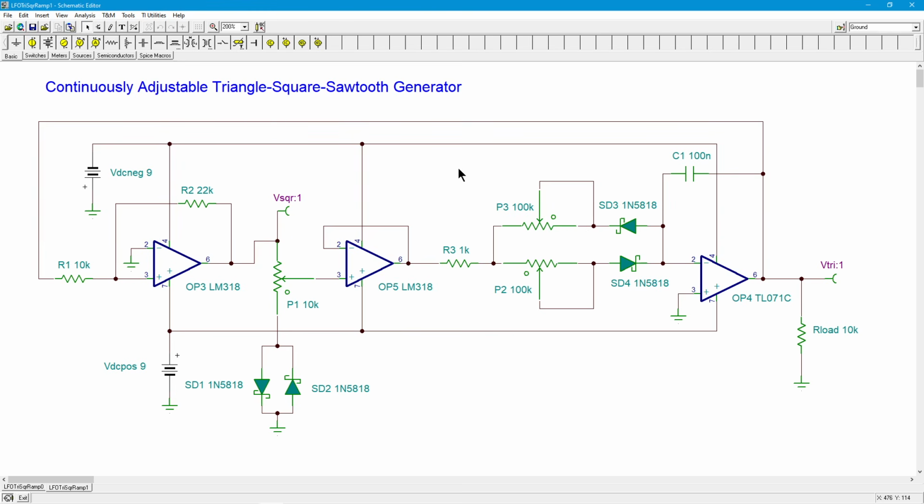Now here's the cool part about this. We take two identical potentiometers. We actually go out and we buy a dual gang pot, right? So two pots on one common shaft. But we're going to wire them as rheostats and we're going to reverse wire them. In other words, if you were looking at the back of this, right, there would be three terminals. You have a left terminal, a center terminal, and the right terminal. So the center terminal is going to be the wiper arm. And I'm just going to say that's your left terminal. This is your right terminal. In one case, we're going to use the left terminal and the center terminal. In the other case, we're going to use the center terminal and the right terminal.